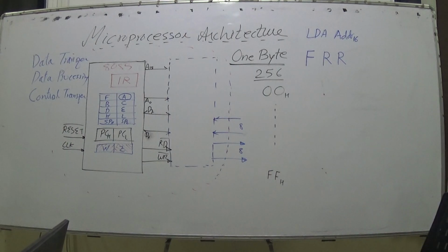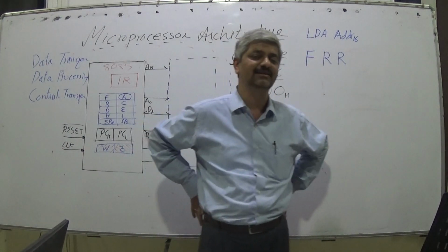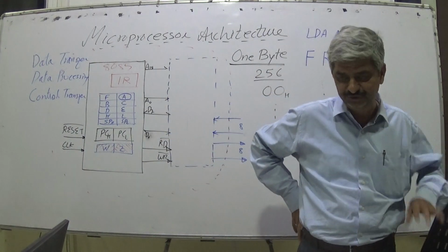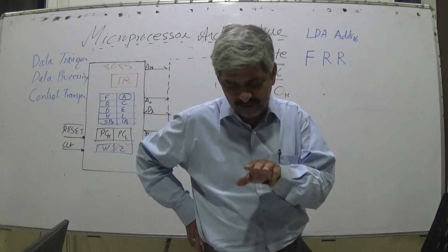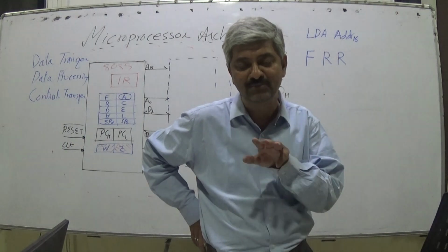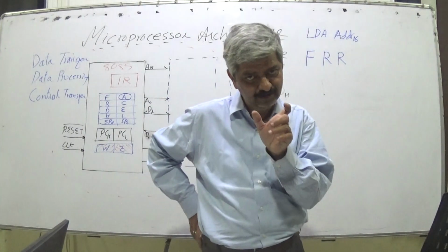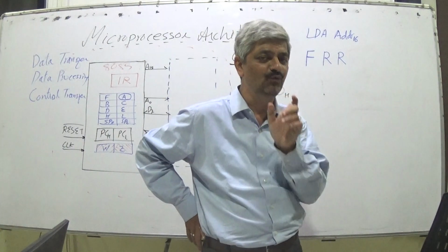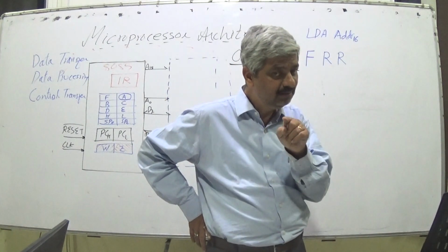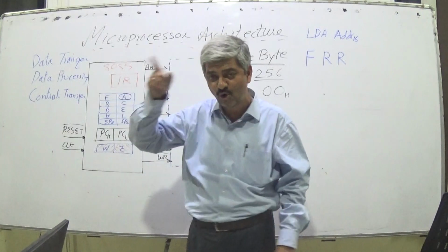Microprocessor performs complete reading of an instruction in either 1, 2 or 3 machine cycles. Performing one memory read or one memory write is done in 3 clock cycles. 3 clock cycles is 1 machine cycle. So the microprocessor performs one complete instruction read in either 1, 2 or 3 machine cycles. And how does it know? When the first byte is read, the instruction register knows